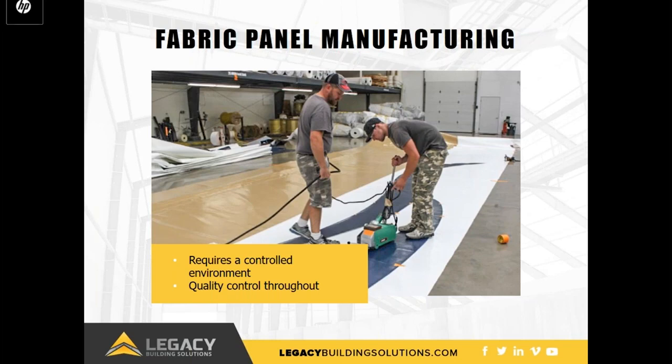Once panels are cut and aligned, individual pieces of fabric are welded together using hot air, wedge, or RF welding systems. The strength of the fabric weld should be the same as the strength of the fabric itself. Once the fabric panels are manufactured, they can be rolled and packed for shipping to the building location.